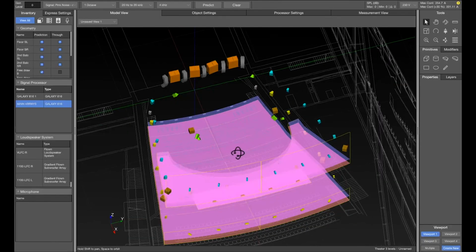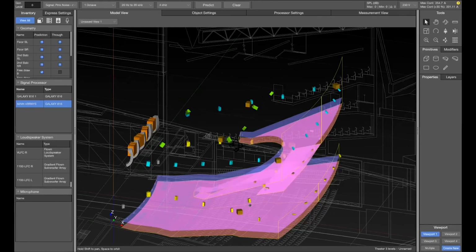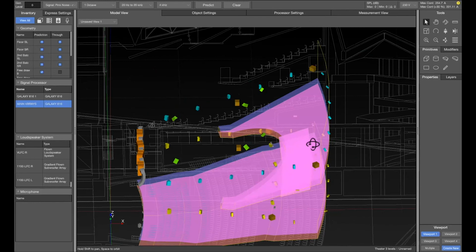Now, if one is farther away, that 1 volt might need to go to a bigger speaker that's 6 dB louder to throw twice as far to get to the same SPL. So what I'm going to do is work around this Spacemap Go box to get things to come in at equal level, to enter into the zone at around the equal level, and things that enter into the zone will also enter in around the same time. This is a room that's designed for even coverage and even immersive coverage across the area.